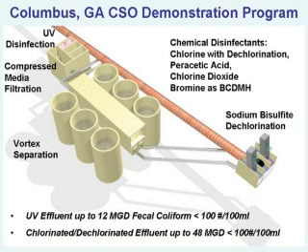The removals from the compressed media filter are in the 80 to 90% removal. And even during wet weather, it produces pretty consistent effluent. The infiltration, if you can take the high solids loadings, what you're going to find is that the effluent from a filter system is going to be based on the particle sizes they can get through the filter. So it'll produce a pretty consistent effluent no matter what you're feeding, whether it's a high solids loading or a